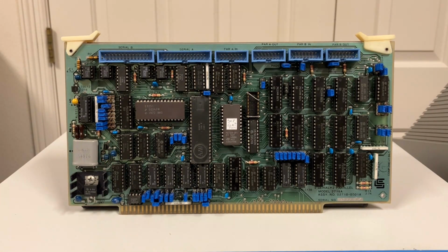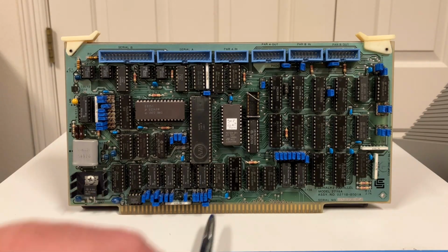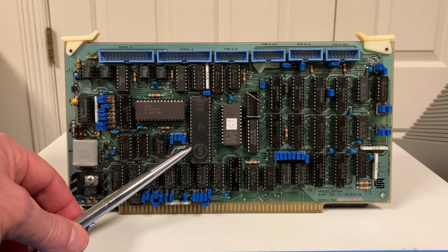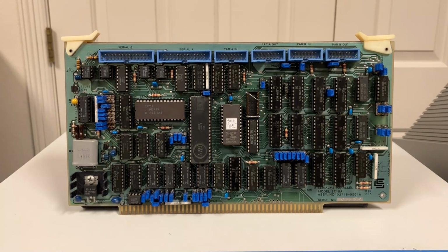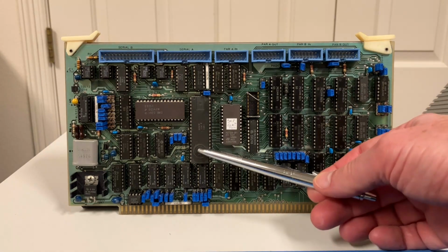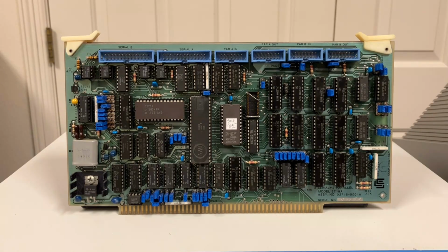today. All right, to get this board working like we need for cassette interface, the first thing we need to do is have the UART that we're going to use show up at IO address 6 and 7. Now on this board, both serial ports are set with a single set of jumpers, these right here. And what those do is set a group of 4 registers at address 0, 4, 8, etc. So I have this set right now to put the 2 UARTs at address 4. And now we need to make sure that our UART is at 6 and 7 and the other UART is at 4 and 5. That's done with this last jumper you see right here. So presently this is set to put the UART we're going to use at IO address 6 and 7.